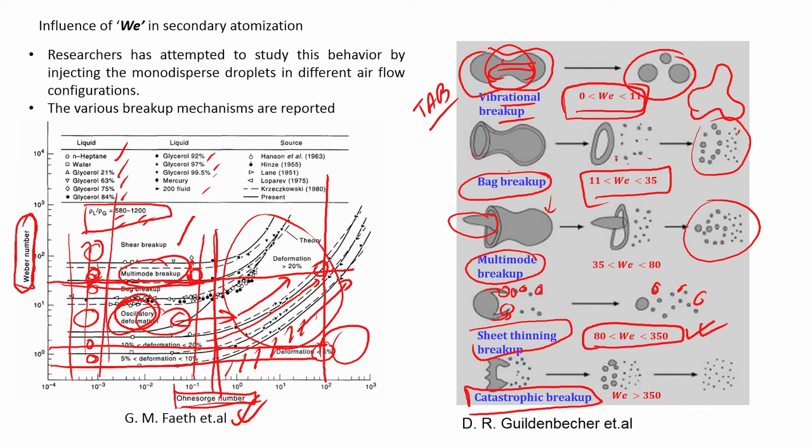The breakup is so violent that there is no fixed pattern in it, unlike this one, which has a particular sequence of events. First it inflates, then there is this protruding ligament and then it breaks up. Okay. Here it first thins along the sides and then the side starts to atomize. So, there is a process, there is a certain time sequence history, right. This actually atomizes all of a sudden, it is violent atomization, which happens for very high Weber number